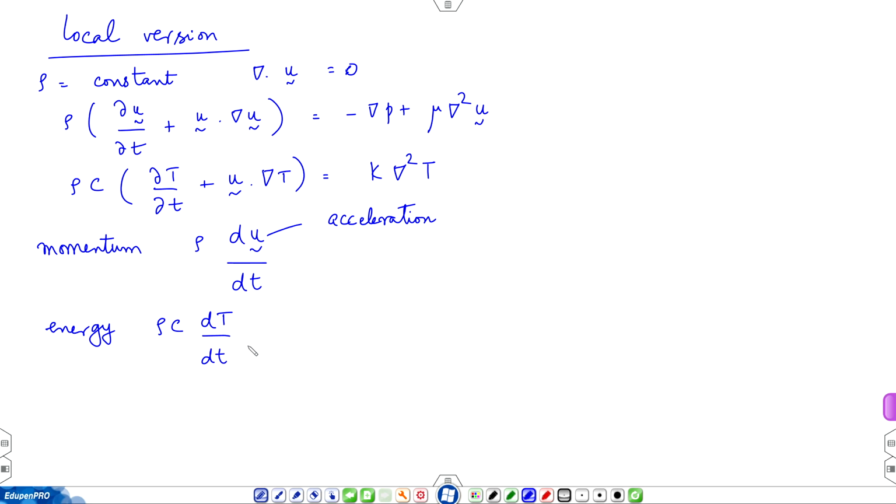So, this term, like acceleration, is the temperature content, which is internal energy being carried by rho c I times temperature will give you, well, actually I plus p over rho, as we had discussed, which is internal energy plus p over rho, which is enthalpy being carried by the flow. So, it is thermal signature being carried by the flow, like acceleration. So, there is an analogy between the two, except that acceleration is a non-linear term, this is a linear term.